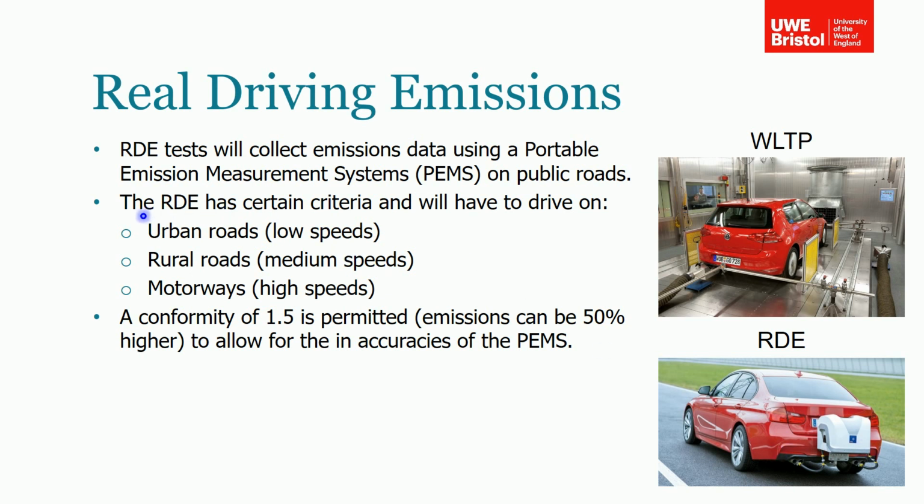And the vehicle isn't just taken out and tested in any old road conditions. There are still certain criteria the vehicle has to meet. It has to drive on some urban roads at low speeds, some rural roads at medium speeds, and some motorways at high speeds. And there's various legislation that the test has to be more than a certain period of time, and the elevation change can't be too much or too little, and you've got to have certain percentages of low, medium, and high speeds, etc. So it's quite a lot that is needed to make a valid RDE test.